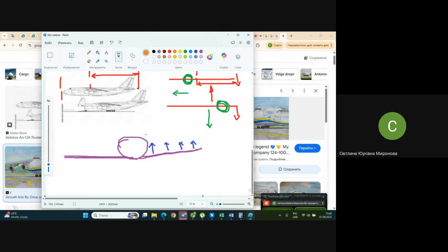The bending moment, as I already said, the worst for us. Also the so-called shear forces, their distribution, the load diagram, approximately corresponds to the external loads in general view. But the bending moment at the tip of the wing is equal to 0. There is no force yet, so practically no bending moment exists here.